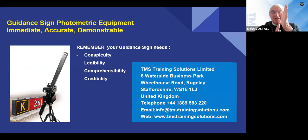And so at a particular distance, now bear in mind, we've discussed 150 meters in terms of the design of guidance signs. Well, if we took an angle and then took that line from left and right and took it back to where those two lines, a line perpendicular to the fascia, cross the center line of the taxiway, then we could determine what that angle is.